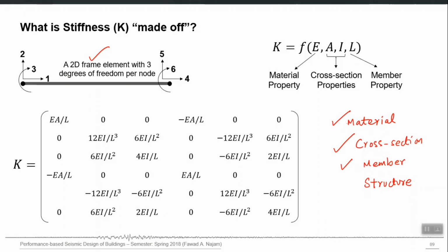So simply by understanding the flow of stiffness from material to full structure level, you can also guess that at what level I have the opportunity to introduce the nonlinear action in this flow, so that the relationship between F and U may not remain linear, right, as assumed in this case, right.